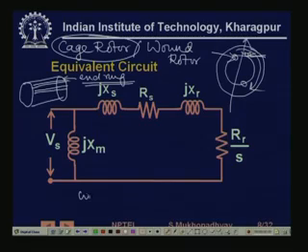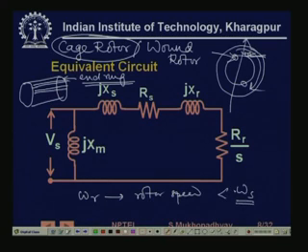So, the rotor will rotate at a speed which is close to synchronous speed, which is called omega r or rotor speed, which is less than omega s typically if you keep the supply constant. So there is a concept of a slip, which is defined as (omega s minus omega r) by omega s. This is called the slip or sometimes the slip frequency.